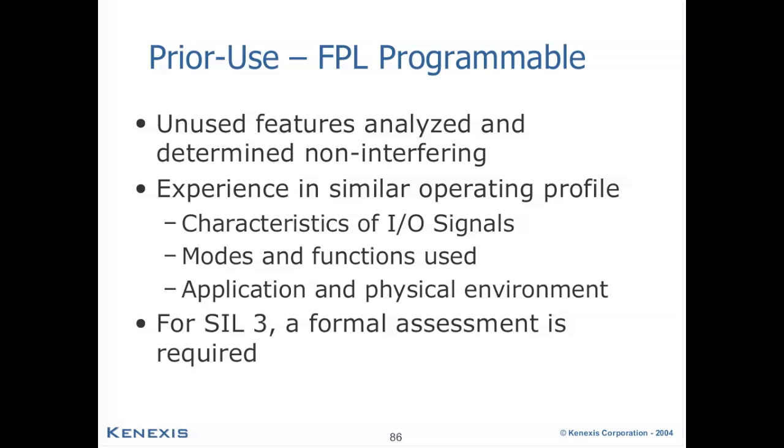And you must demonstrate that the component has experience in a similar operating profile. Namely, you should monitor the characteristics of your input and output signals, the modes and the functions used, and observe its use within a similar application and physical environment. And additionally, for SIL 3, you will also need a formal assessment.